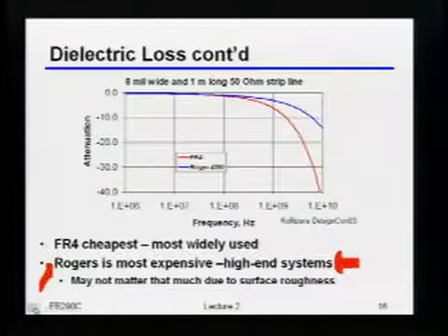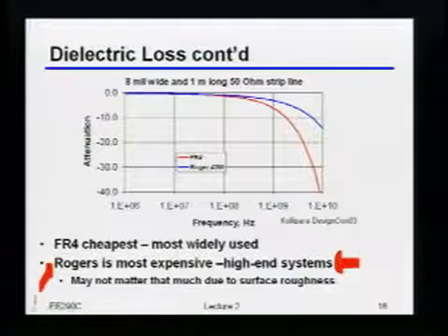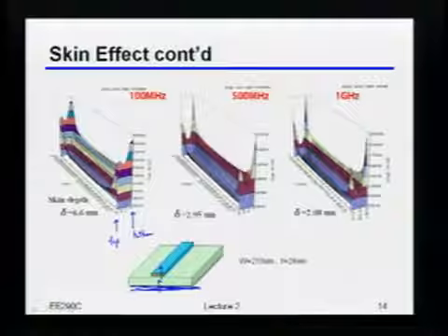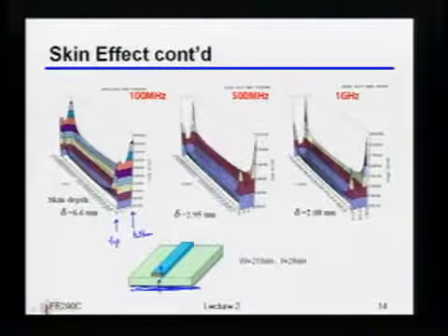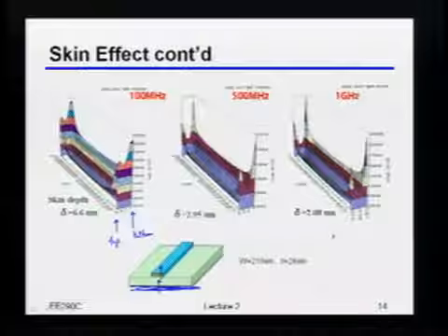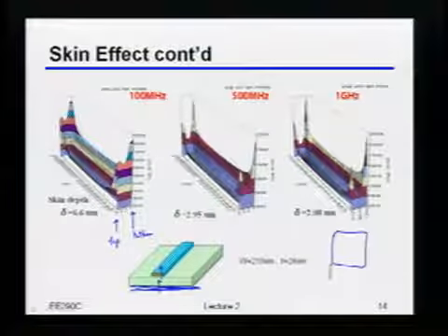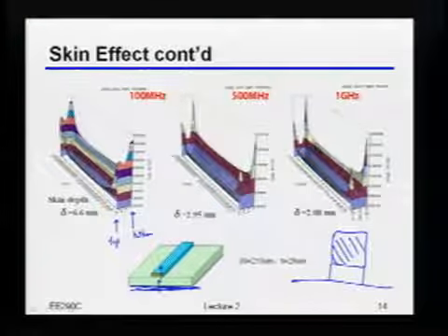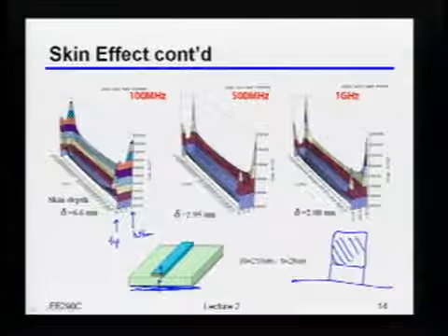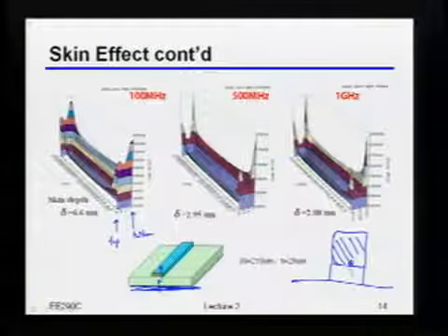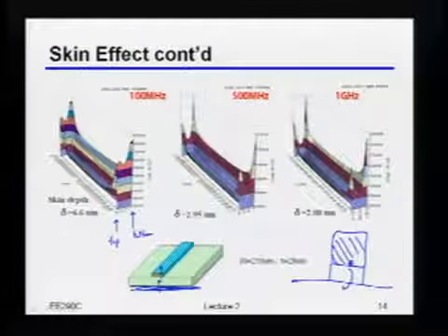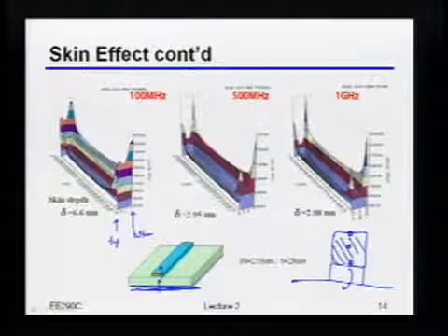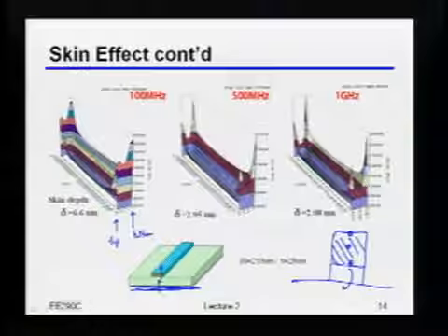We're a lot higher on the bottom, obviously, because they're attracted to the... You're talking about over here? Yeah. So they're attracted to the electrons. Exactly. So all that's really happening here is if we draw, let's say, a little zoom in of that picture, if I've got my conductor over a ground plane, then all you're trying to do is minimize the loop that's going into the page and then flowing back out through the ground plane. Because if I've got current flowing out, let's say over there or in the middle, it has to flow back through a longer loop.